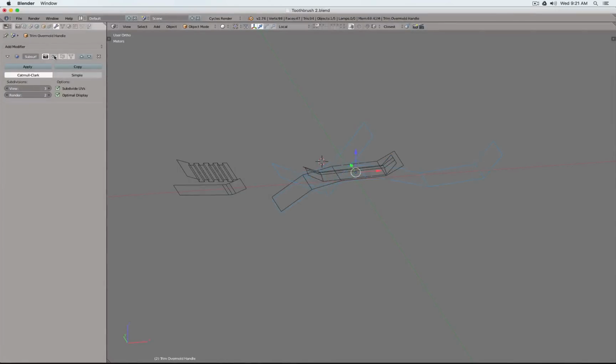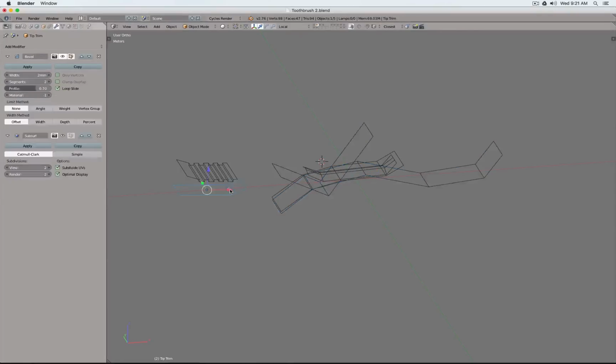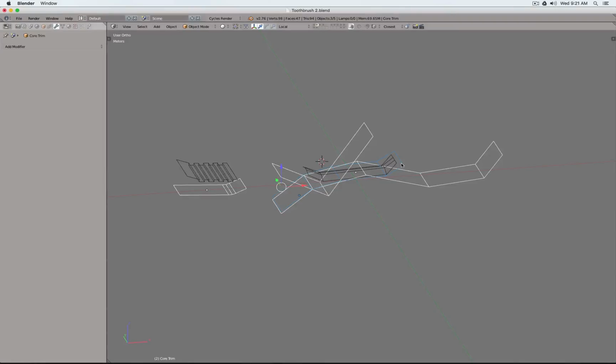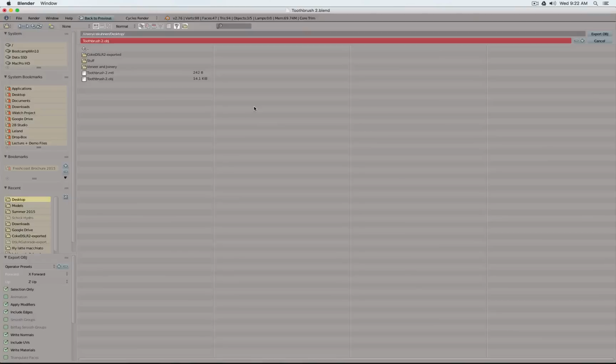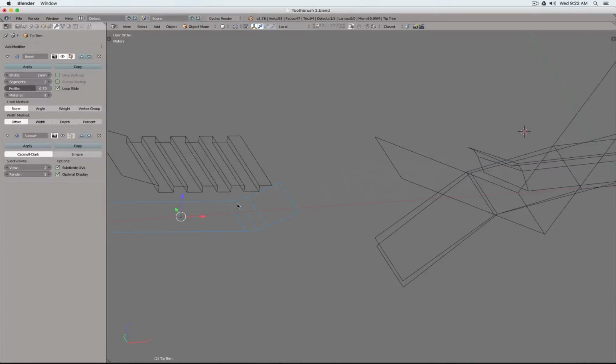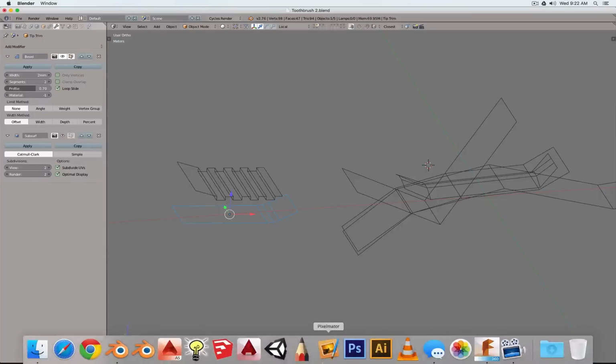Because this one uses a bevel command, I would like to export all at the same time. So I quickly turn the subdivision surface off for all those. Then I can press spacebar, export OBJ, select it only, and apply modifier. Notice apply modifier will create the geometry from the bevel command here in Blender inside Fusion.